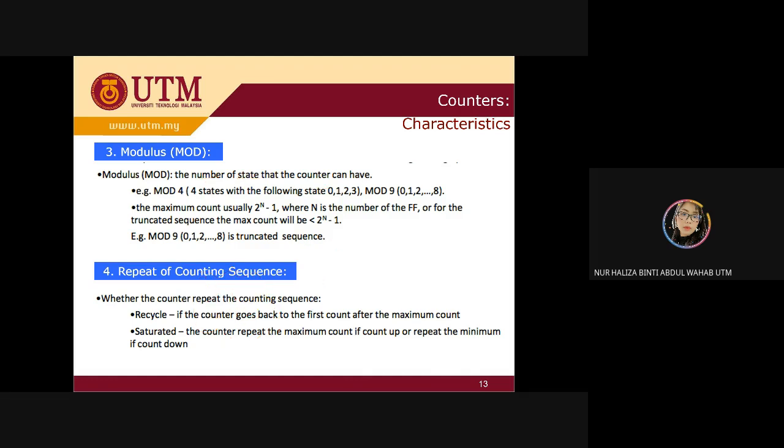And under your modulus, after that, you're going to look into whether it is a repeating sequence or not. If you have repeating, it's going to be recycle. And if you have saturated, the counter repeats the maximum count if counting up, or repeats the minimum if counting down.